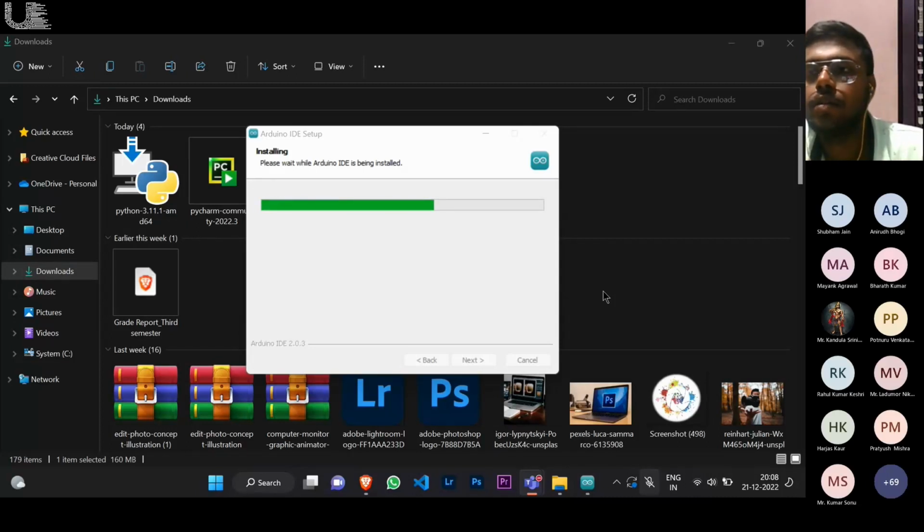So Sachin, hi. Arduino you can power with a USB connection also. When you power with a USB connection, there is no need for a dedicated power input pin to be connected to the Arduino. By USB, it can both access the code as well as take power from the USB connector itself.